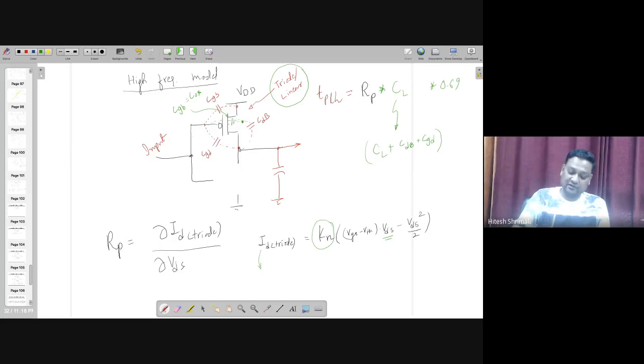Notably, when we are doing this analysis, I'm assuming that you are well aware that VDD is not moving, it's AC ground, and input is also not moving, because we assume that it's either VDD or ground, so it's also ground. And for ease of calculation, the rest of the capacitances will vanish, because between input and output it's a short circuit, because both sides of this capacitance are the same plates, they are not dissimilar.